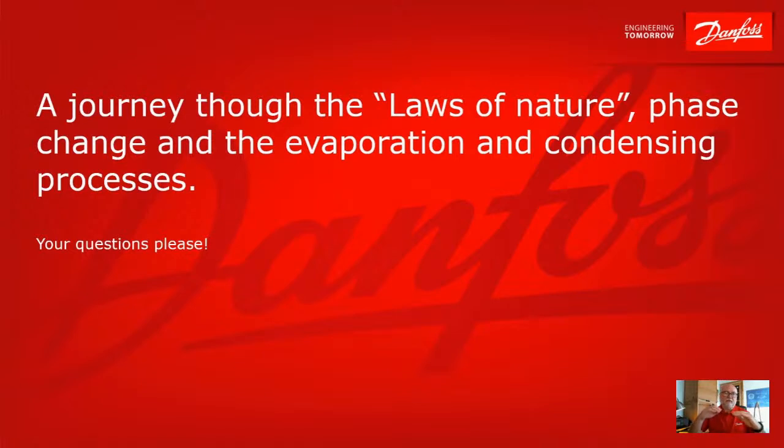Then the 5 degrees from the 10 degree to the 15 degree would be your superheat. Usually you would measure that in Kelvin, but the happy thing about Kelvin and degrees Celsius is that the difference is 1, basically. 1 Kelvin is 1 degree Celsius.